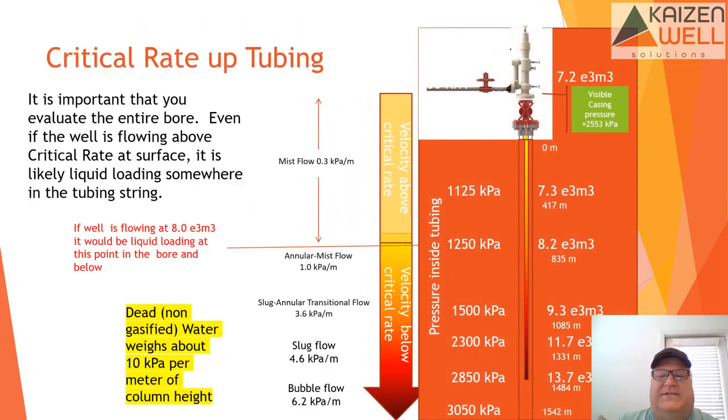Another interesting thing is that you can see, and I've seen this a lot in gas wells with water, especially production, where you can be slugging in the bottom areas of the tubing in some of the deeper wells, and you have a hard time getting liquid all the way to surface, so you'll be slugging and carrying on. And of course, as that slugs in there, it starts to liquid load when you get more and more weight pushing back on your formation, the rates start to drop, and then it slowly builds up and you'll die.